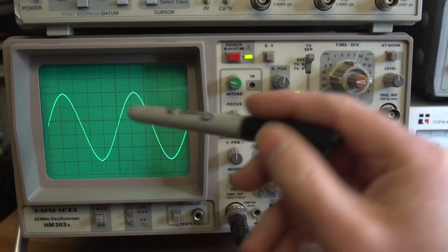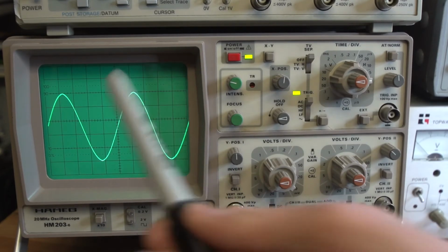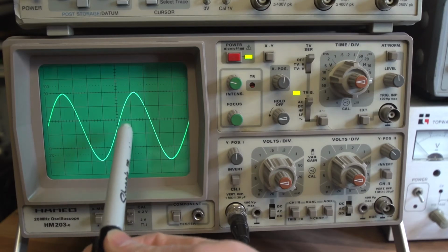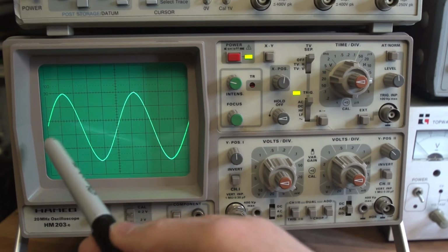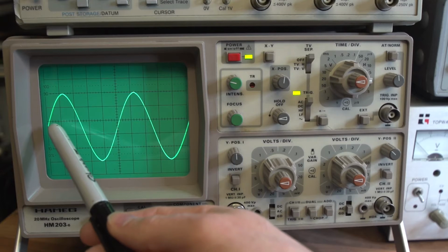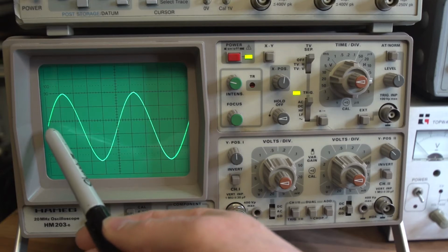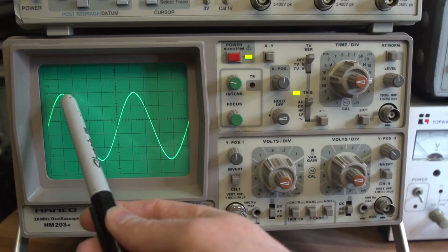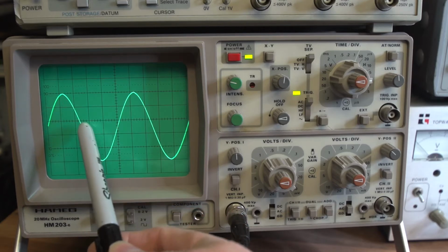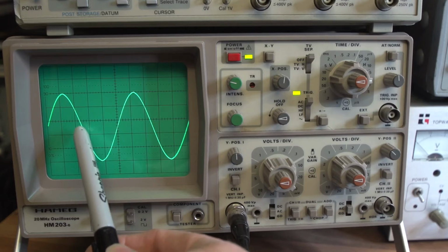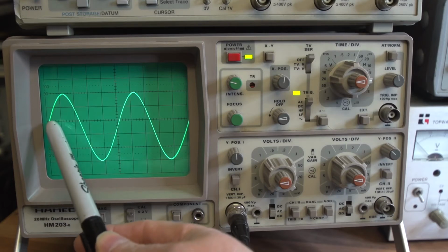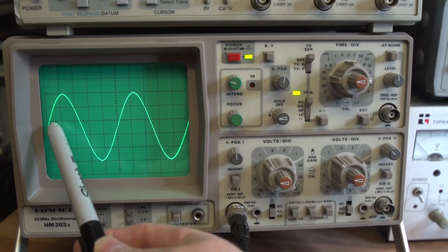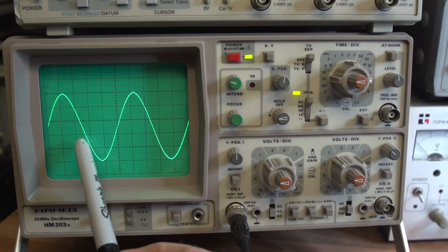Okay, now the other thing the scope is telling us is the frequency, or the time duration it's taking to go from one part of the cycle to the next. You know how big one cycle is by looking to see where the waveform repeats itself. So if you look at the waveform here, it's going up, goes to the top, coming down. Now you might say, well, is that not the same? Is that not one waveform because it's repeated at the same voltage point? And the answer is no, because that one was going up and this one's going down, so they're different.